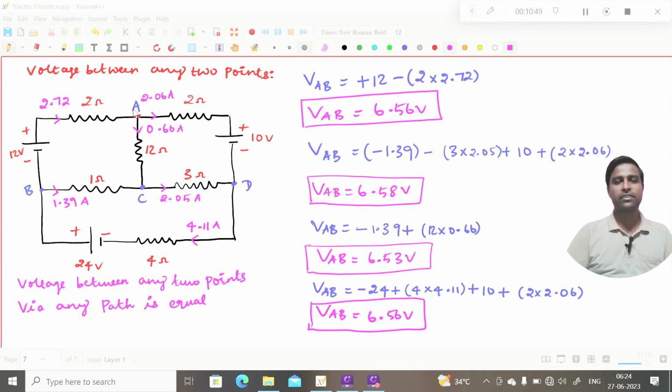Thank you. We will see different topics in the next class. We have seen voltage sources, and we know how to write the KVL expressions now. While writing the KVL expressions, at last we found the loop currents and then the resistor currents, the current flowing in each resistor. We also know now what the voltage between any two points is, and power balance. Up to that we have seen.